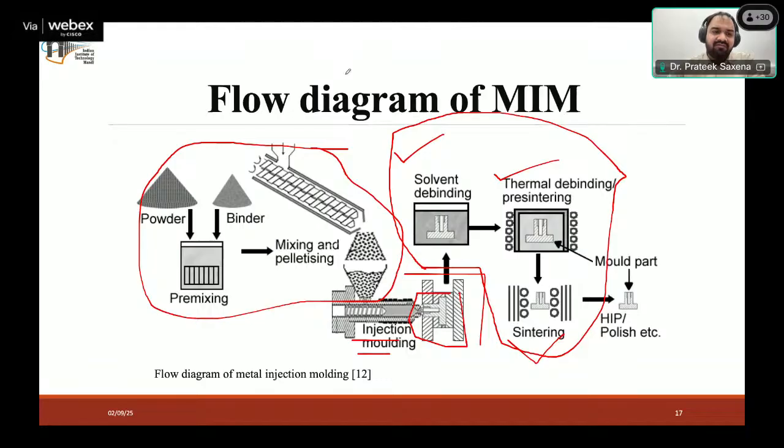See, when you have metal powder and you want to join it together, you need to add heat to the system. In some cases heat plus pressure is required. But the kind of temperature we are talking about here for metal additive manufacturing, for example metal injection molding, is something around 1300 degrees, 1400 degrees, 1500 degrees, depending on the kind of metal powder that you are using.